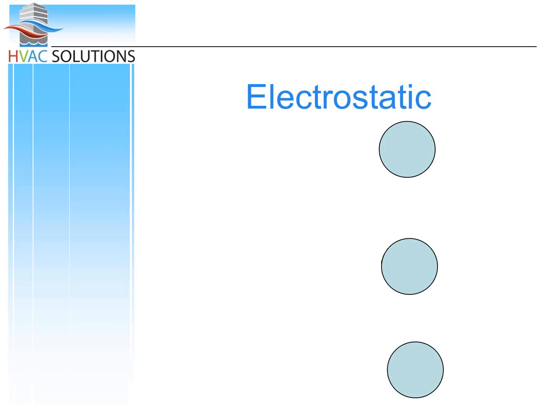TFP stands for Turbulent Flow Precipitator. So, not going to ask you to remember that one, because it's crazy terminology. But what this really means is that if we can slow down airflow, I can make filters more efficient. So think of a piece of cardboard that has holes cut into it. Say dozens and dozens of holes.